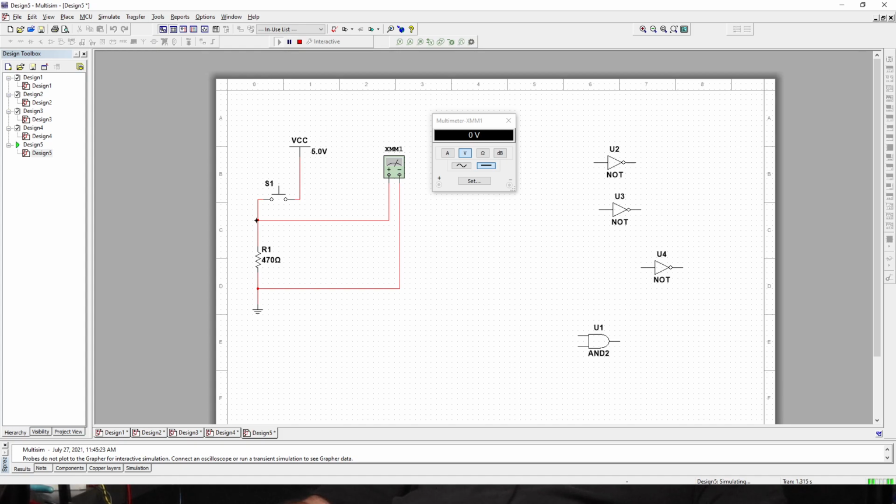And once we push this button, what do we expect? We expect that point to be directly connected to the 5 volts, so we should see 5 volts here. Let's check it out. I'm going to press and hold. Alright, that thing changes to 5 volts. When I release, it changes back to 0. Or if I press momentarily, it's going to have momentarily 5 volts, but this multimeter doesn't have enough time to react to that. Okay, so we have confirmed that our pull down system is ready for us.